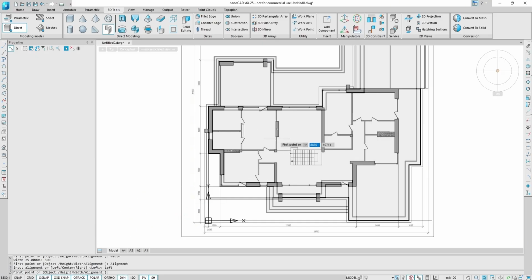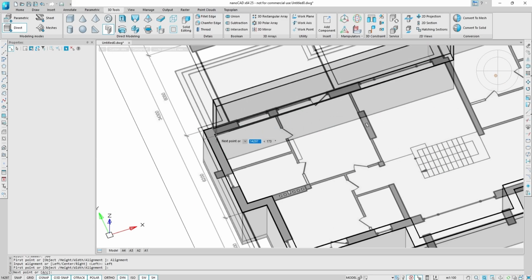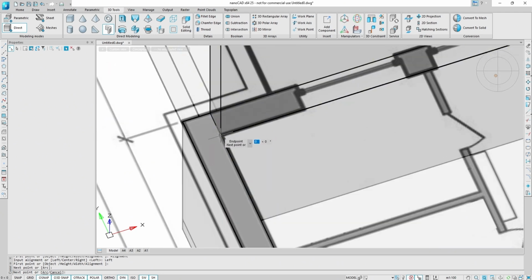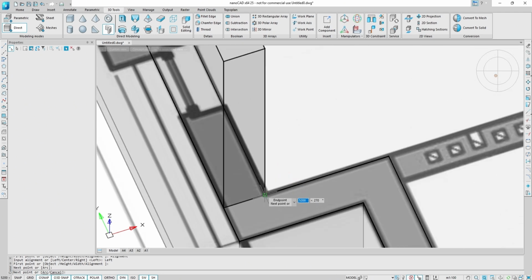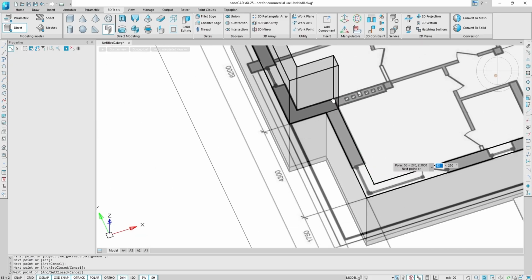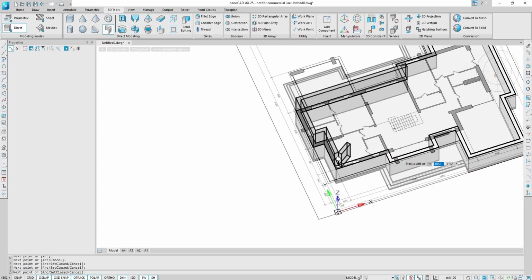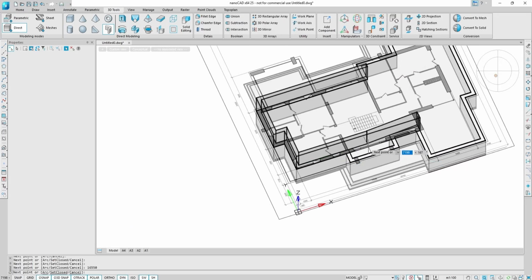We start from the first point, using bindings to the walls of the first floor, and then set only the lengths or bind to existing walls. Left 14,650. Down 5,200. Right 1,500. Down 4,300. Right 16,550.